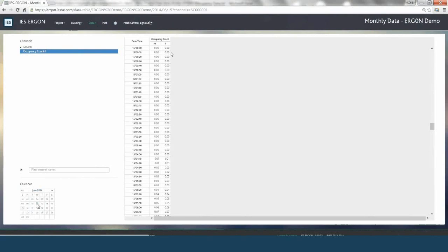At this point they're both set on 10 minutes, but like I said, if you had data on half hour or 15 minutes on your metered column, and then you had your ERGON set to be 6 minutes, then what you would see is there'd be white space in the metered column, and the interpolated column would be showing some red text, which would essentially be interpolating the missing points. So that's worth a look at. So that just again lets you check the quality of the data.